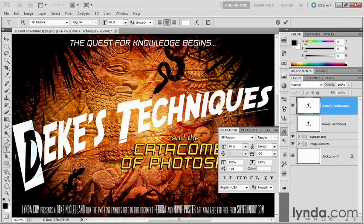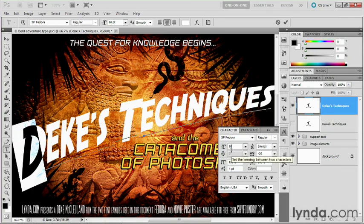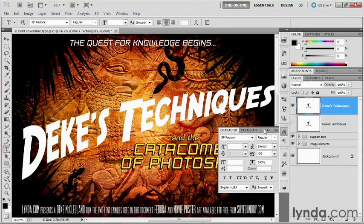Next, select the D, and Photoshop may automatically assign your last formatting attribute, in my case, baseline shift, which is just fine. So we want a baseline shift of 4 points. We want to reset the vertical scale value to 100% and then take the type size up to 60 points like so. And then press the Enter key on your numerical keypad in order to accept that change.